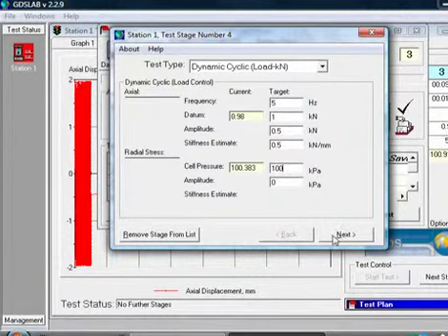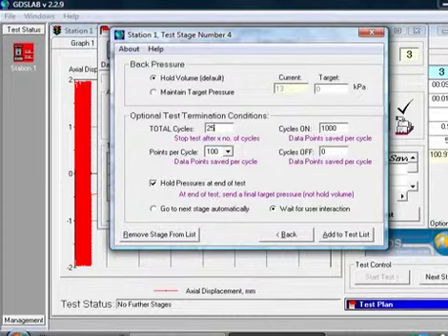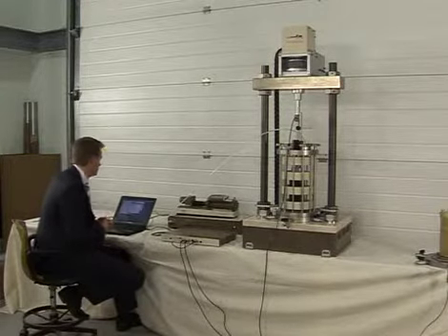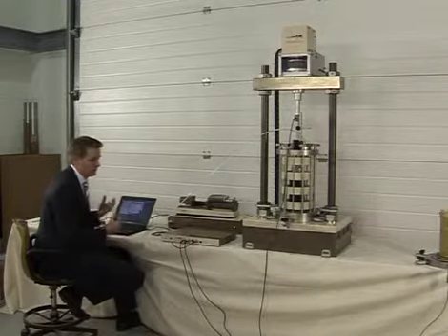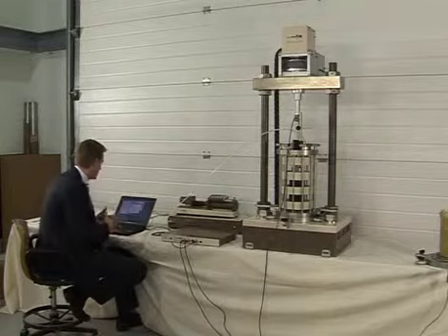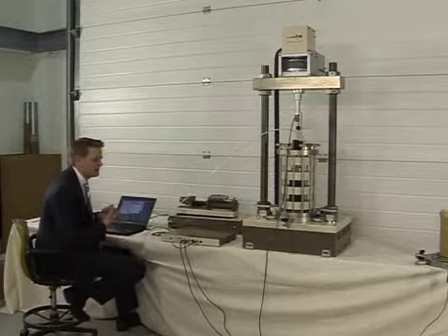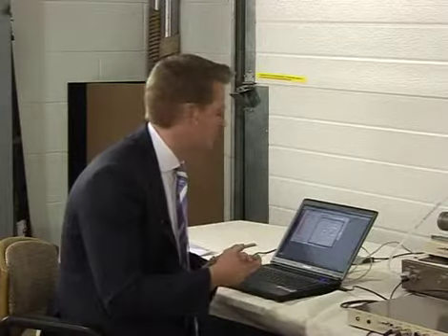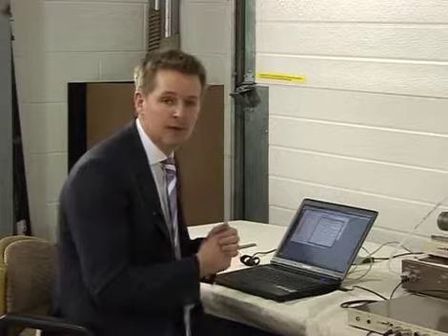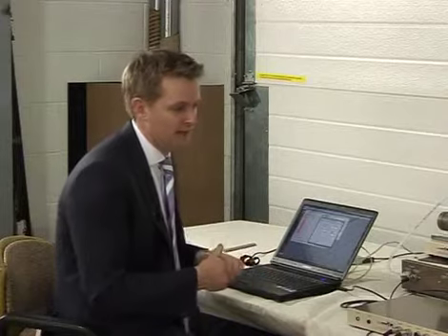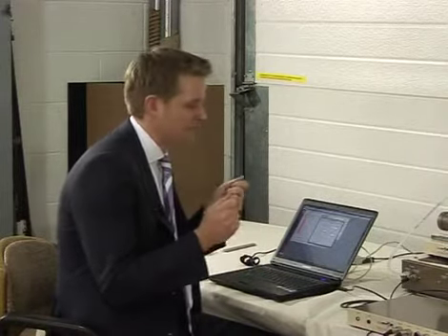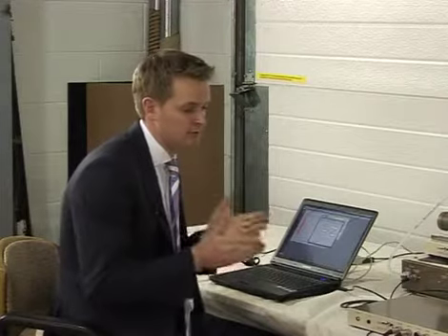Again, let's have the number of cycles as 25 like last time, and let's just remind ourselves what cycles on and cycles off means. We've seen that when we do a short number of cycles, say 25 cycles, we can easily download all of those cycles at 100 points per cycle and display that on the screen. If we want to do a very, very long dynamic test, maybe one that's going to last a number of hours or even longer than a number of hours, half a day at maybe 1 Hertz, that's an incredible amount of data for the software to extract out of the control box.